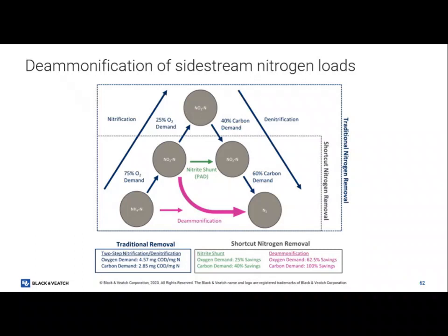They want to be aerobic. They need air to do their processing. So they're taking NH4 out here. As they go through, they're converting that to NO2, which these guys want. But these guys don't want DO. So as you go through this granule, DO actually decreases too. So 1 DO out here might be a 0.1 DO in here.